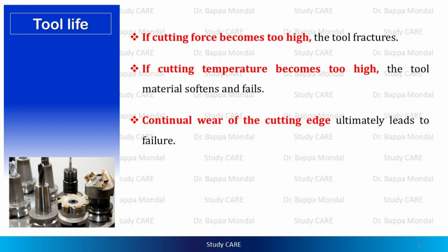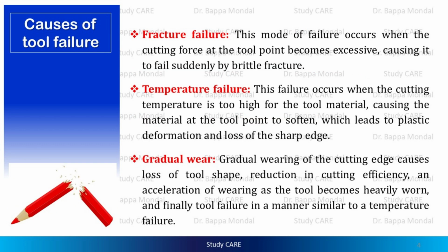If cutting force becomes too high, the tool fractures. If cutting temperature becomes too high, the tool material softens and fails. Continual wear of the cutting edge ultimately leads to failure. Three main causes of tool failure.